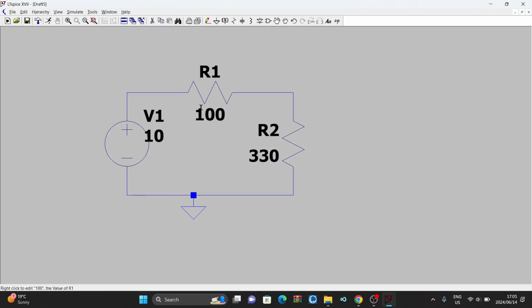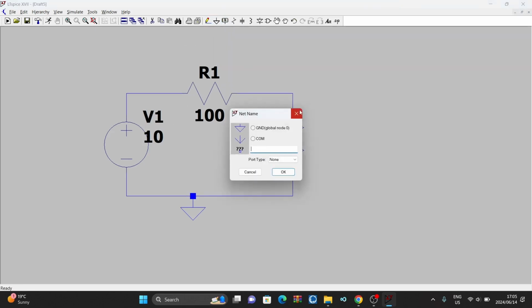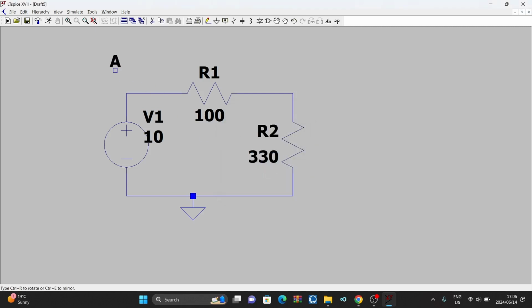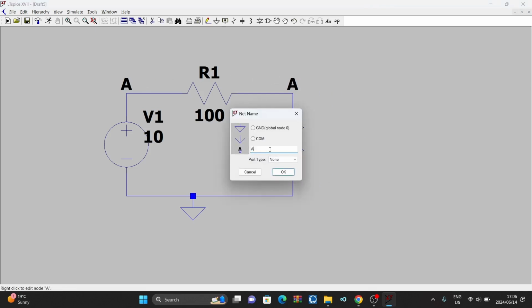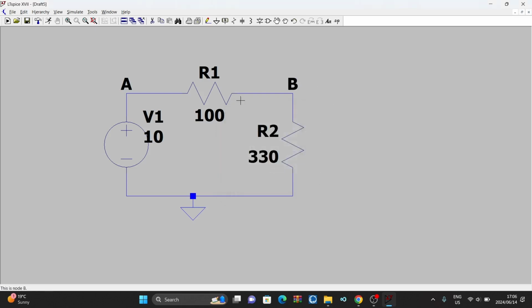Right now I want to check the voltage, let's say, and now we can label different points, and you want to see what is the current, right? So here you have your label. You just click, then this window pops up. Then you can label it any name I want. I label it A. Press OK. So this is my point A. Then to change this value, just right click on this. You can change it to B. So that's my point B.